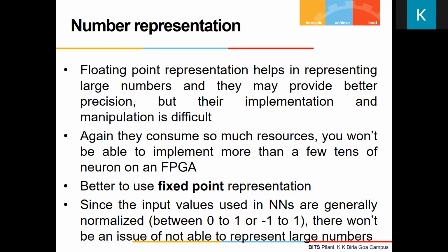Floating point numbers are very suitable for multiplication; you can easily do that. But when you do addition and subtraction using floating point, that circuit has to be more complicated. So if you're using FPGA tools, you cannot directly write it in your Verilog. It won't work.